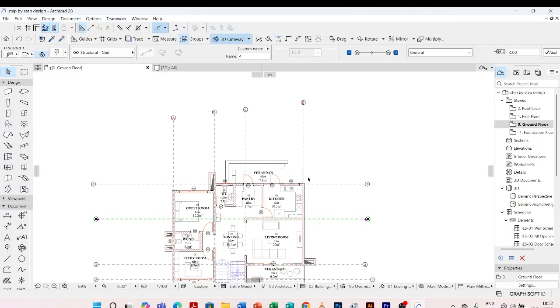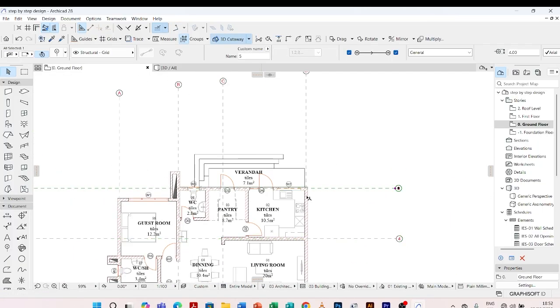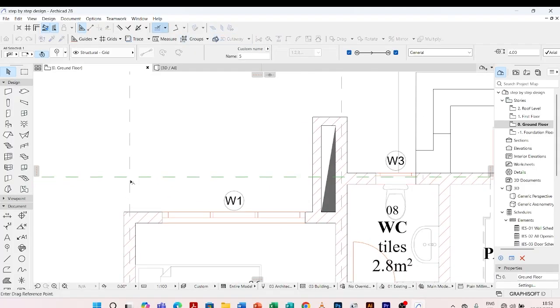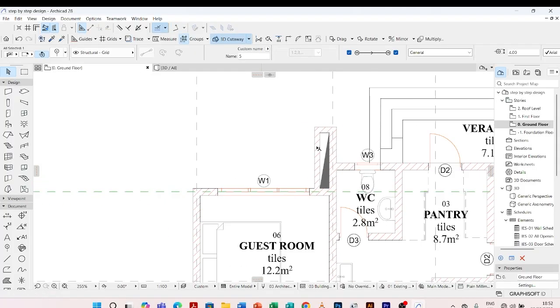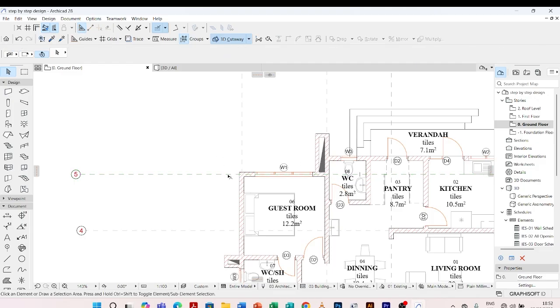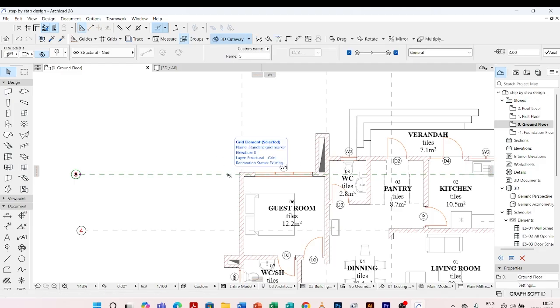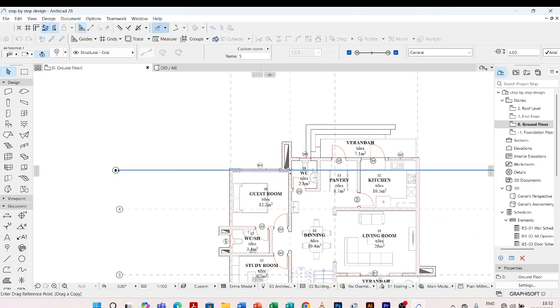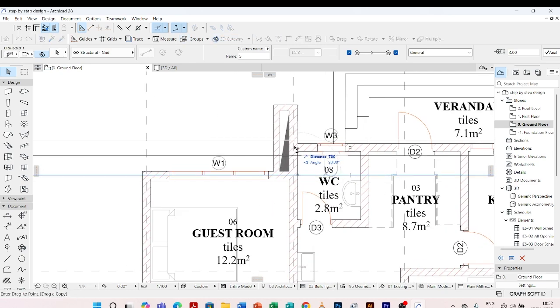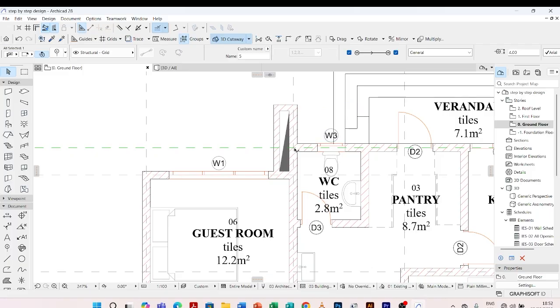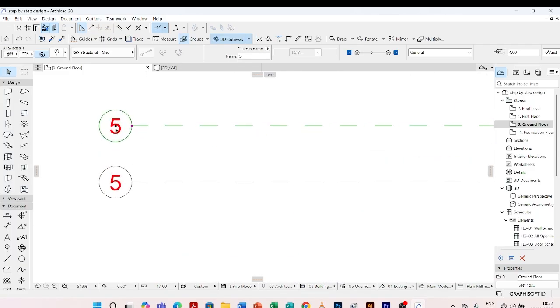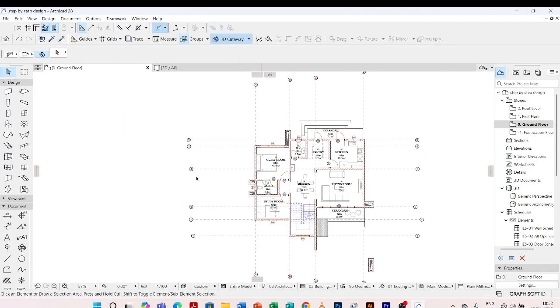The middle there. I'll drag the fifth one, Control D, up to there. Then the sixth one, I can drag a copy of this one. How do I drag a copy? I'll type Control Shift D, that is for dragging a copy. I drag it in the middle of this one. So I have to change its naming to be 6. So I'll come here, type in 6, that is okay.